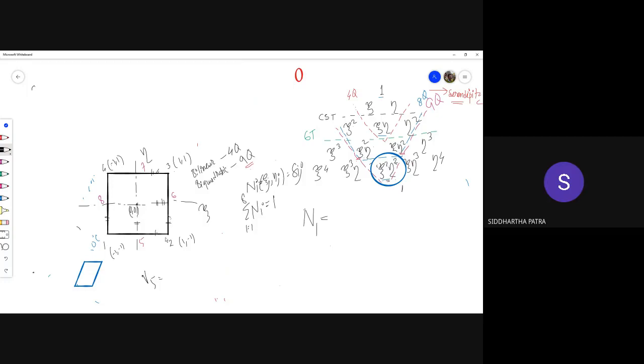But by taking 2, 3 and 3, 4, you have already made it 0 at 2 and 4. Just understand that there is no node number 9 now. At the center there is no node. You are not supposed to make it 0 at the center. So what you would be doing is taking line 2, 3, line 3, 4, and then line 8, 5.